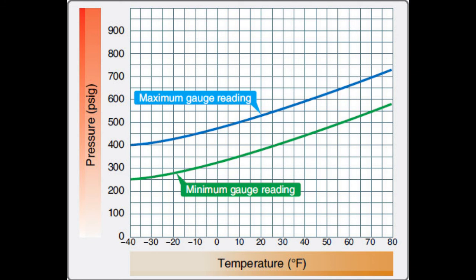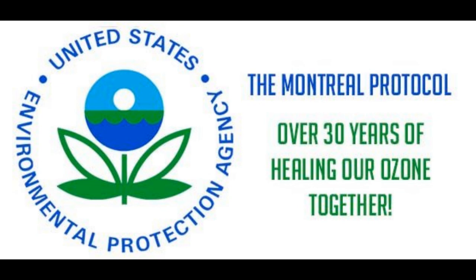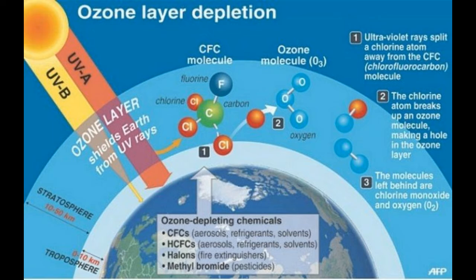I spoke before a little bit about the ozone depletion potential of these halogenated hydrocarbons and the problems those cause. The Montreal Protocol was signed in 1987 and called for a total ban on the production of many halogenated compounds, including halons, in 94. So they agreed that they would stop producing these, but the existing stockpiles have been reserved for the military and aviation, so there is still some access to that. And we also have an exemption. Basically, it lays out that certificated aircraft manufacturers and owners could still have access to 1301 in order to meet the requirements of their fire suppression equipment, because no agents that could meet those requirements had been found at that point.